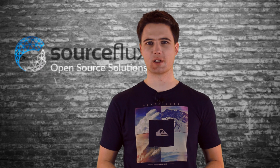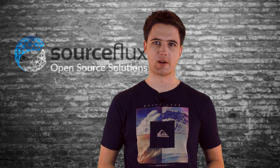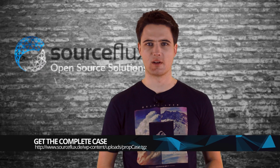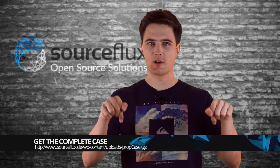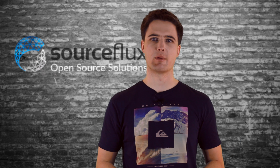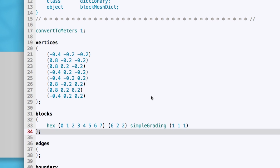After the blockMeshDict has been cleaned up, I'm going to add the vertices for our case right now. If you would like to skip this step because it's tedious and time consuming and error prone, you can just download the completely configured case from the video description and skip this step. After these 8 vertices have been added to the blockMeshDict, it is a fairly straightforward task to add all of them to one big block in the blockMeshDict.